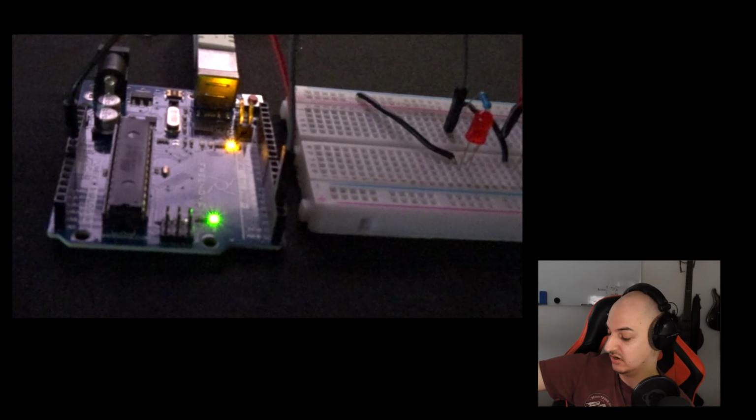So it's important that we add a capacitor. This little boy here, I've got a 4.7 uF one. A 10 uF is recommended most of the time, but I got it to work every time with the 4.7. And what we're gonna do is take our board. We're gonna see where the minus leg is. Usually it's marked with dashes. We stick that one on ground, or the shorter side in this case, and the other one to the reset port. So now we've got a capacitor between reset and ground.